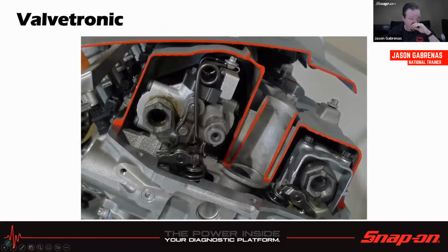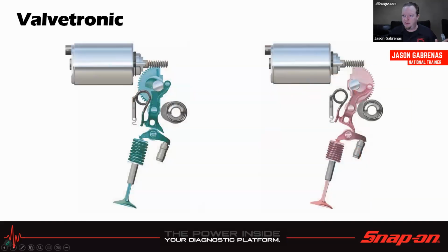All right, now let's move on to electronically controlled variable valve lift, which would be BMW's Valvetronics system. That uses some solenoids that change the profile of the rocker, and that works in a similar fashion, right? So we have these little solenoids here, and you can see how the rocker is kind of shifted down like that. The camshaft pushes over here, so this is an eccentric.